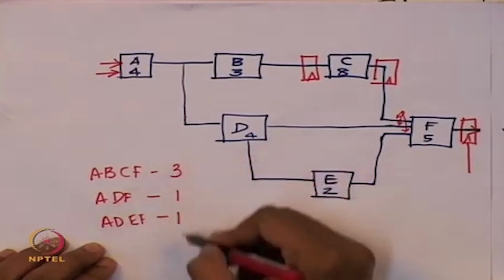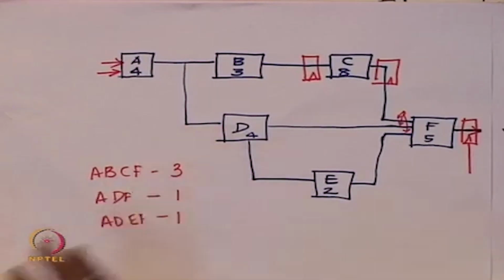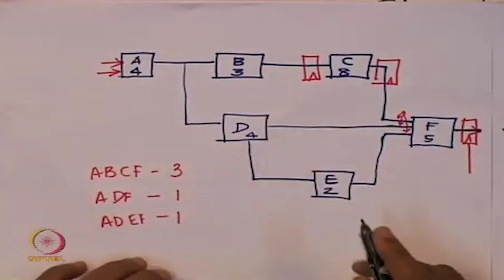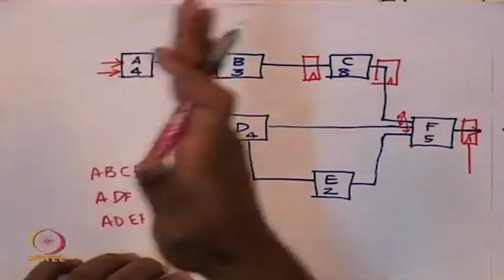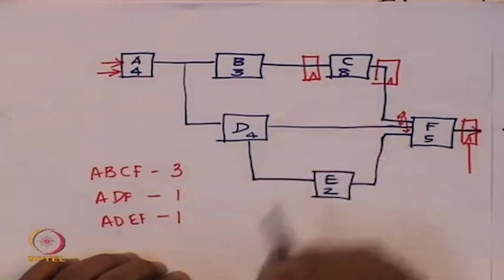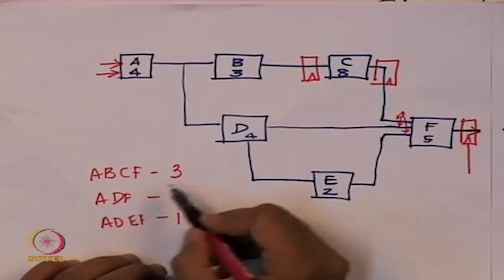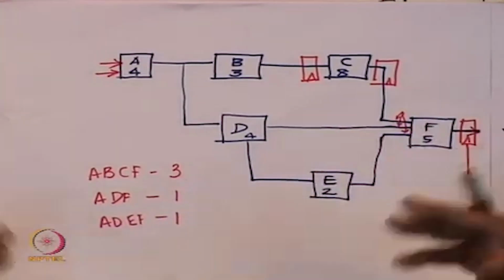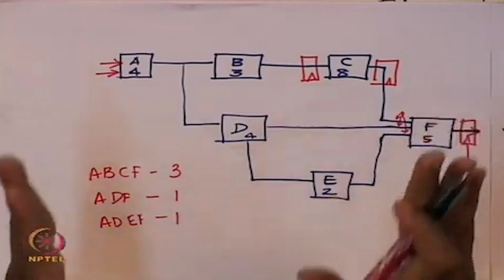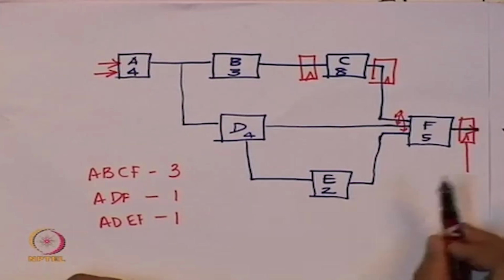flip flop. This is not a well formed pipeline, and if it is not a well formed pipeline, then inputs from different stages are getting mixed at different points. That is not correct. So we want the same set of inputs going through different stages going to the final output. So we want to make this a 3-stage pipeline, right? So I already used 3 flip flops, so maybe I will make a 3-stage pipeline, or even maybe a 4-stage pipeline. But as of now, I want to see at least can I make a well formed 3-stage pipeline, alright.